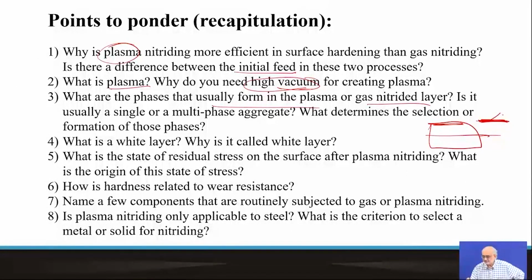So this could have Fe2N, very high nitrogen containing compounds, and as you go down, gradually not only the concentration of such nitrides decreases, even nitrogen concentration itself decreases. Somewhere in between you end up getting a diffuse layer which will contain nitrogen dissolved ferrite or solid solution, and below that will be the substrate. So white layer, then interdiffusion region, and then base substrate.